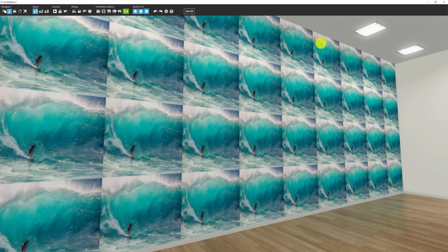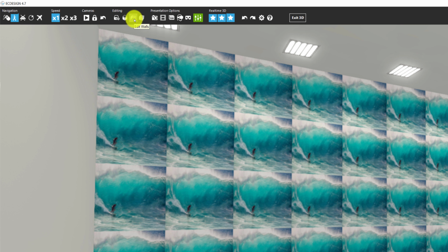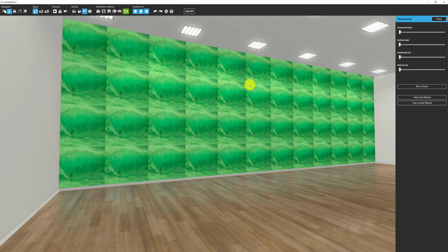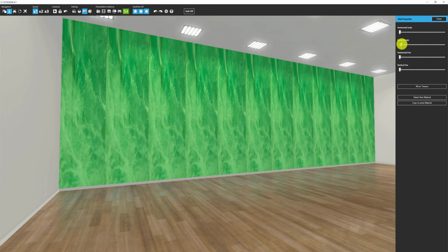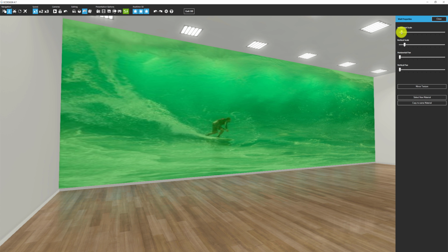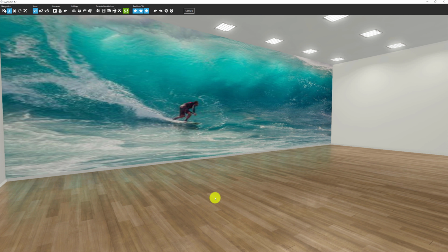Here we go. This is the image that I selected, but for that image to work on this individual wall, we need to adjust it. And in this menu, up on the toolbar section here, we have a wall setting, edit wall. So I'm going to click on that, move over this wall, click on it, and change its scale. So we're basically adjusting it to this wall. And then I click on the outside and unmark my selection right there.